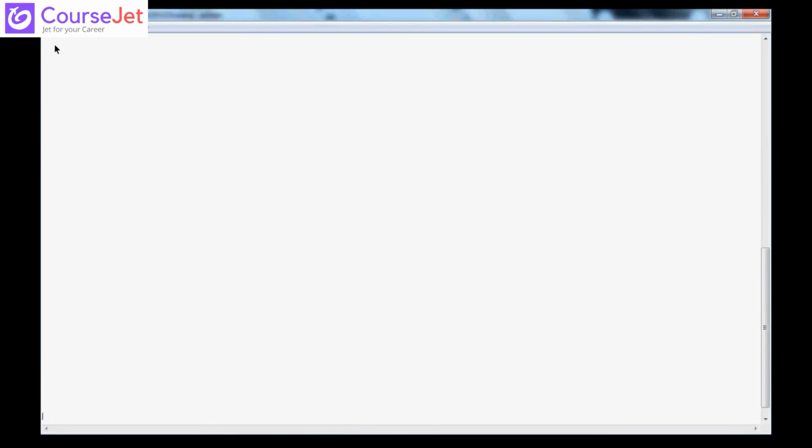When you write something like a 1 millisecond delay and repeat it 1275 times, you get 1 millisecond, but when we calculate, it is not exactly 1 millisecond, it is 1.3 millisecond. That accuracy we don't get with a for loop.